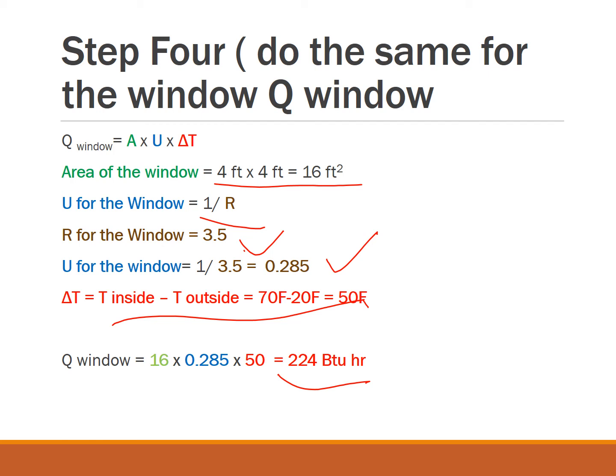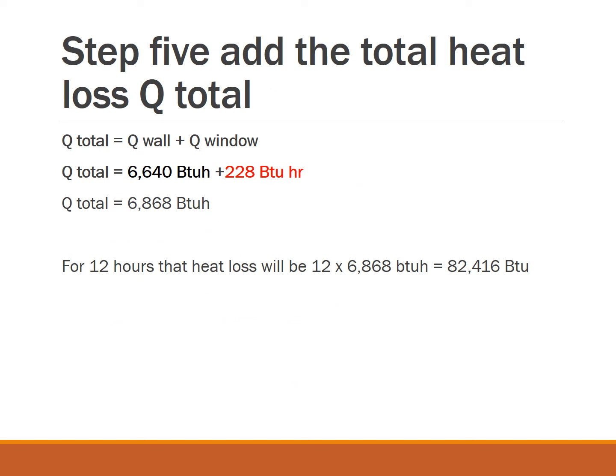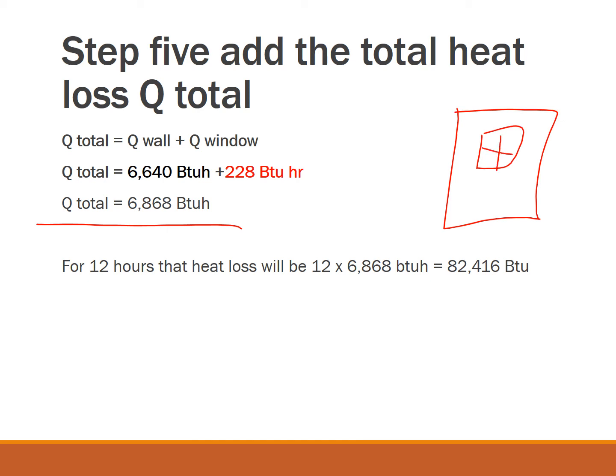So we get the heat loss through the wall and the heat loss through the window, and this is going to be my heat loss for the entire wall, including the window. This is the heat loss from that wall. And usually we do the heat loss for the walls to the outside. Walls to the inside, there is no heat exchange because probably they are the same temperature.